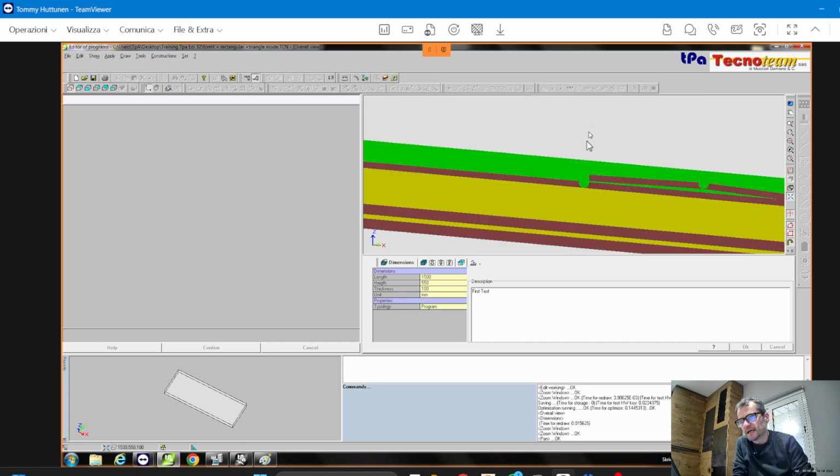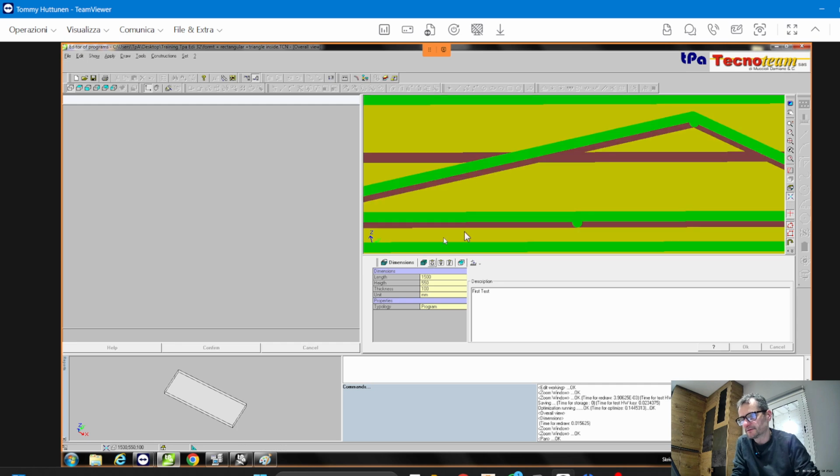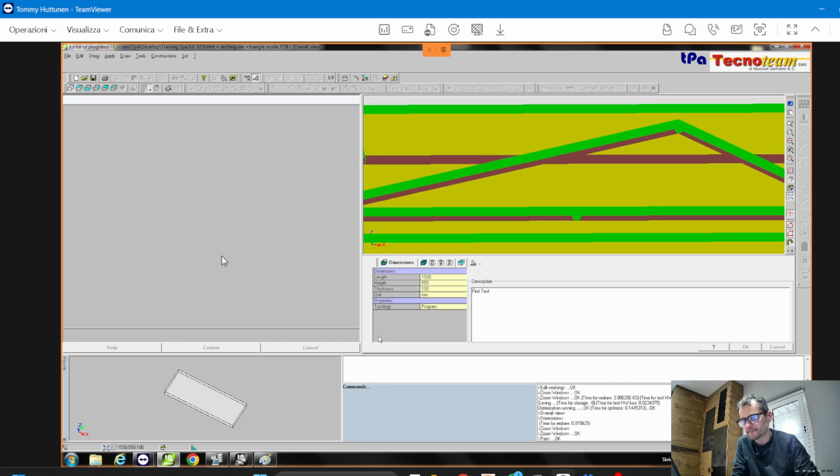So the tool goes down in Z, in the same axis, so just go down perfectly straight on the panel. Like it's a bore, like you have to make a hole. This can be okay sometimes, or not. When is it not? When, for example, I have a big tool, or I have a tool that is not possible to bore the panel. And sometimes it's better to use another way to go inside.